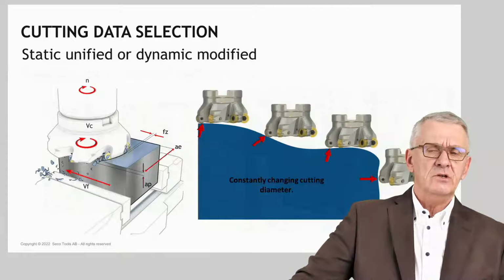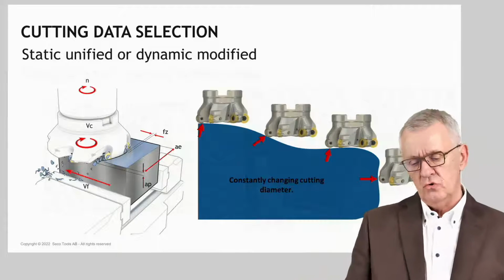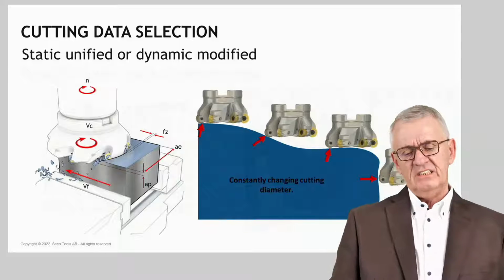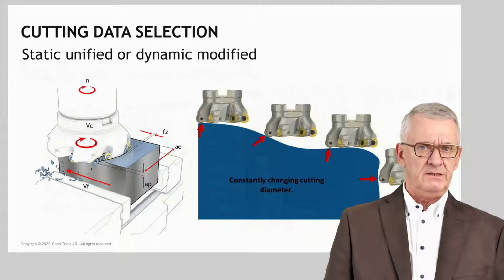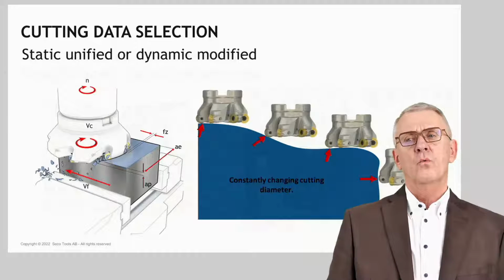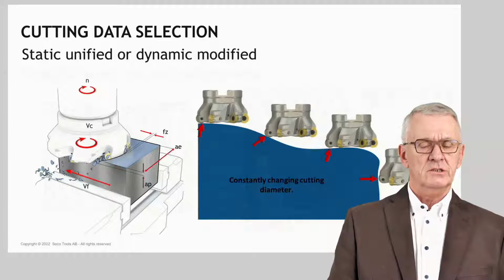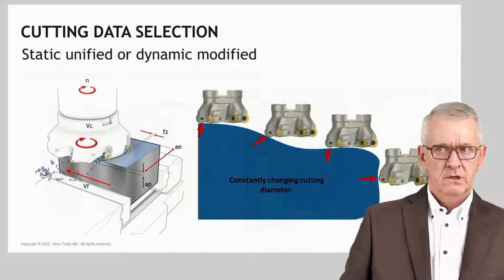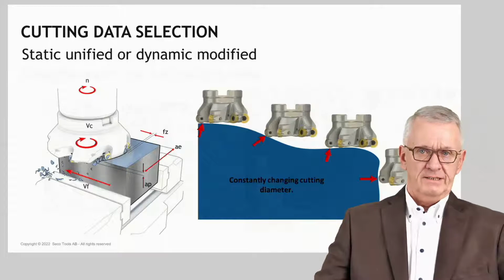And if we think on a philosophy to work with cutting data, there are two very, very distinctly defined approaches. One is referred to as the static unified approach, where you, for once and for all, select cutting conditions for a milling cutter in a certain application, and that's it. Or you go for dynamic modified.